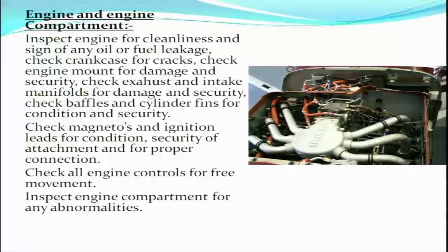The magnetos, which are part of the ignition system of the engine, the magnetos and the ignition leads are to be checked for condition, the security of attachment and for proper connection. All the engine controls need to be checked for free movement, and apart from all these inspections, we need to check whether the engine compartment has any other abnormality or not.